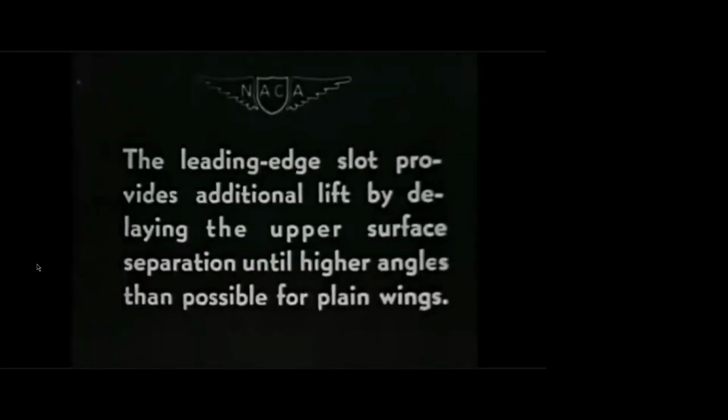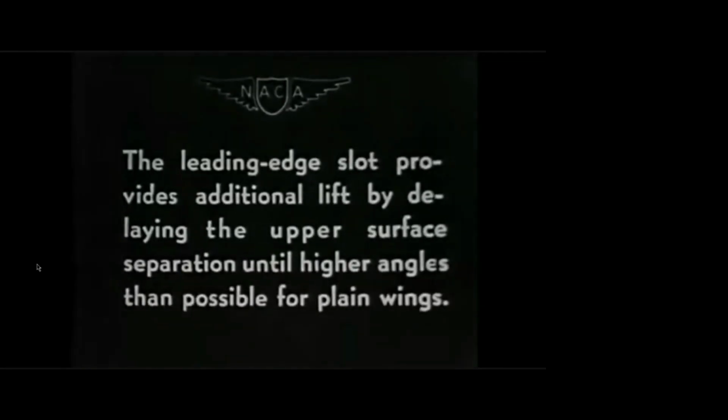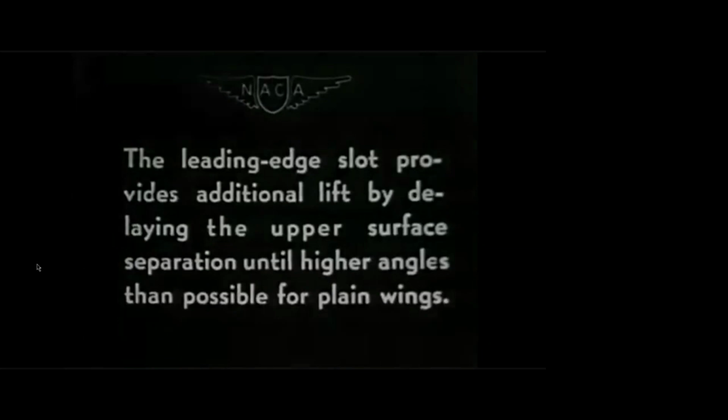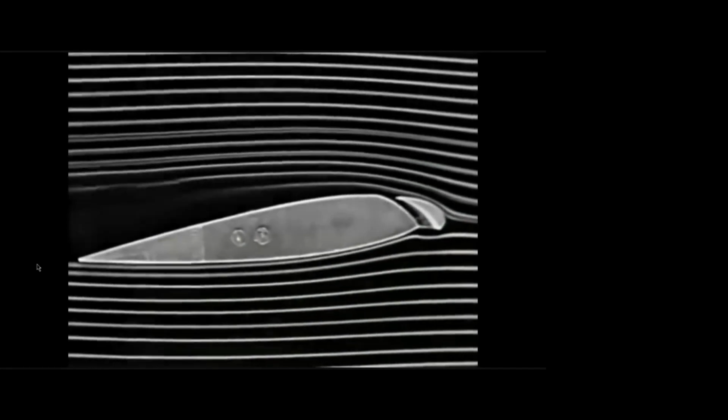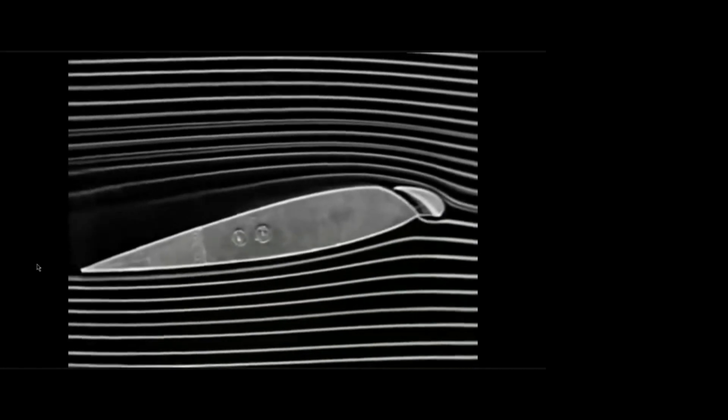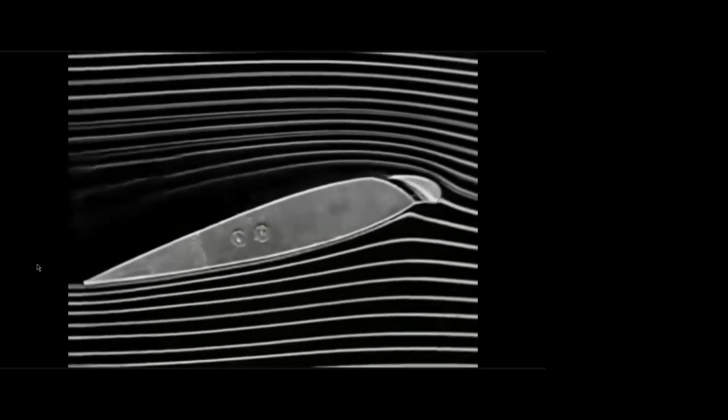Actually, all these flaps, slats and all have to be used only at a high angle of attack. At a low angle of attack, if you use them, it will unnecessarily increase the drag. That's why in cruising, we don't use these flaps, slats and all.